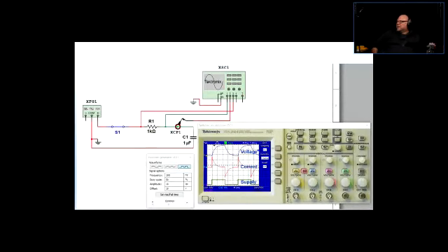Now, here is an interesting slide. You can do that as well. You have access to Multisim. I just Multisimmed a circuit, and I called up an oscilloscope on that, and I turned the whole thing on and applied the oscilloscope as if you were applying this oscilloscope in your lab. The only thing is that you can't measure current. Well, you can, but you have to do some gymnastics when it comes to measuring current, because normally oscilloscopes measure voltage, and you can display the voltage changes on the oscilloscope screen. If you haven't done that yet, you will.